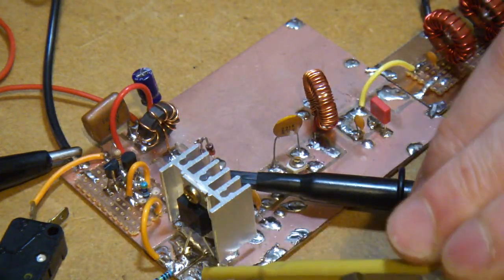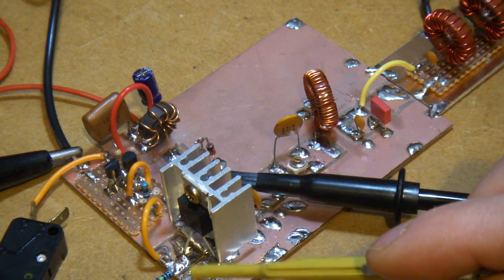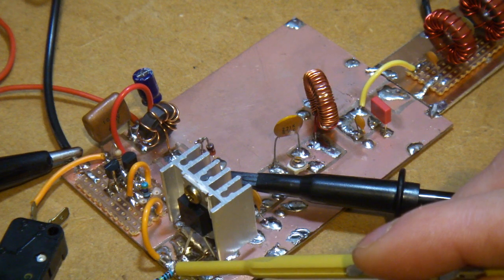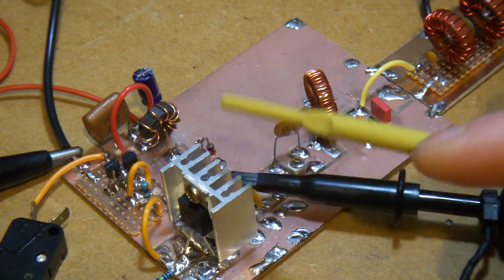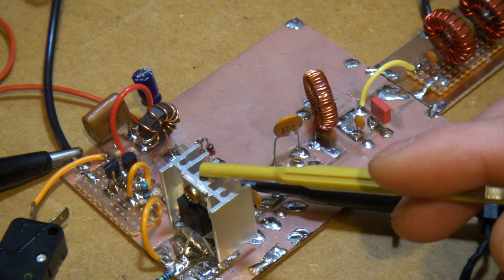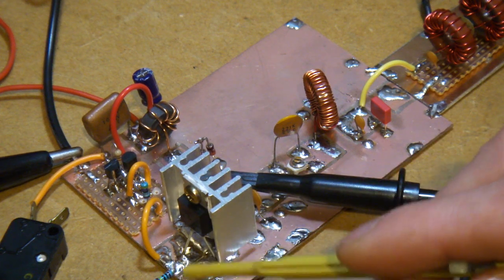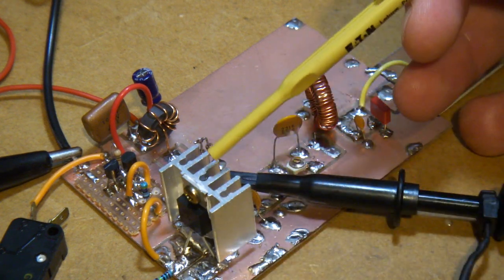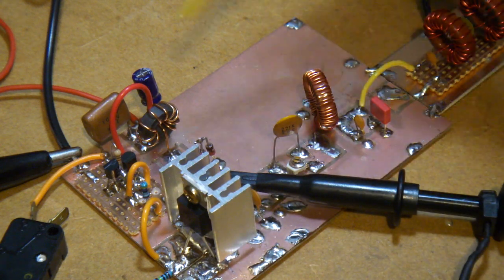And the only other thing which I've left in circuit for this is that 1 meg ohm resistor from the gate to ground. I found if I didn't have that, I was losing quite a few MOSFETs. They were just basically giving up the ghost and deciding to go somewhere else. So by adding that small, I guess it's a bleed of some sort, that sort of mortality rate has dropped right off. So I'm going to leave it in circuit, and it is left in circuit. Other than that, no change.